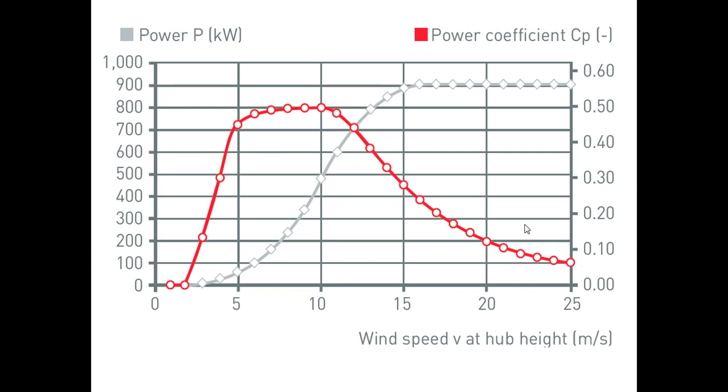Power coefficient. It is the ratio of the power that is to be delivered divided by the power contained in the wind. So it is a function of lambda and beta. As beta is changing afterwards, up to this point of time, beta is almost 0 or it has been pitched with a certain degree. Here I just want to sum up with one example of the fan. If you are using a ceiling fan in our home, it is slightly inclined. That is nothing but the fixed pitch angle. So there are two types of turbine, fixed pitch and variable pitch. These are examples of variable pitch machines.